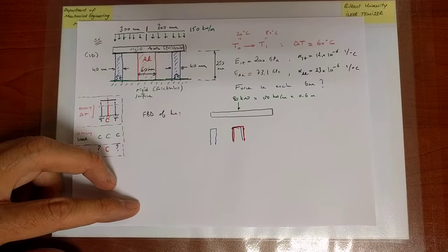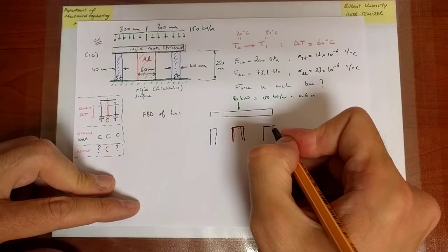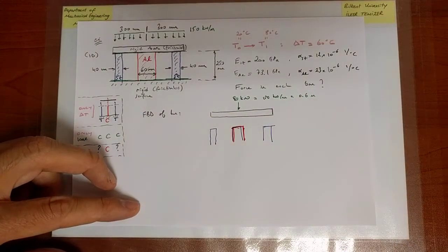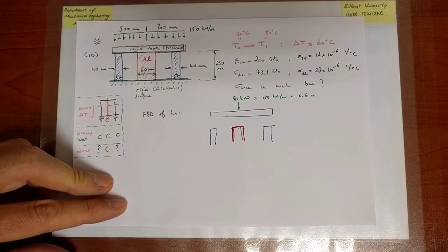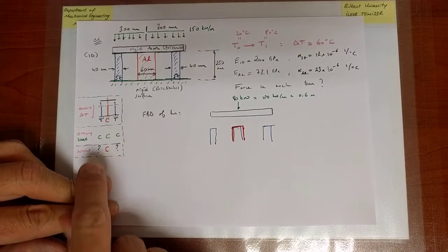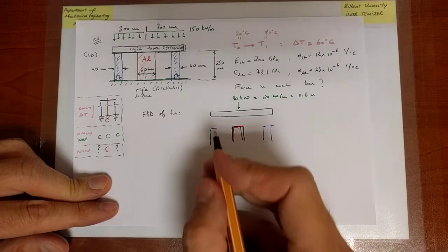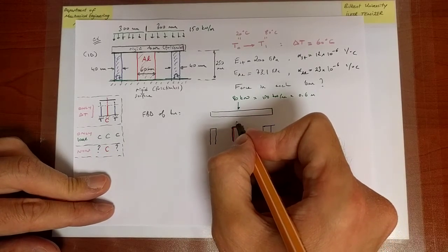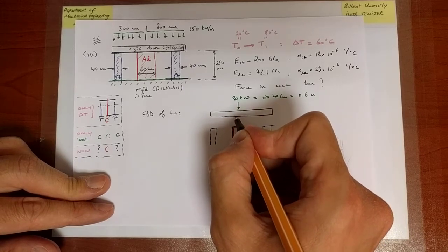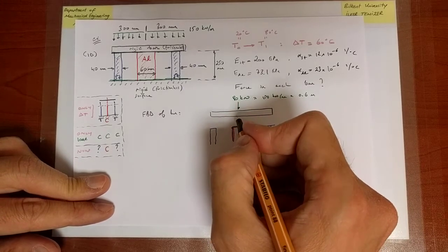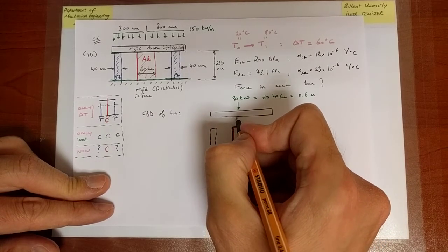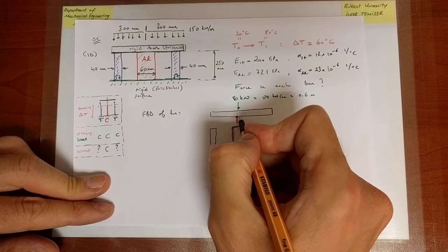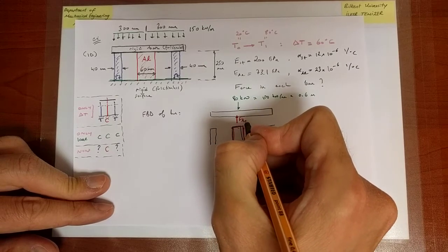And then there is the other aluminum bar. Now, I know that the aluminum bar needs to be under compression. So in other words, the force direction should be like this. So the force acting on the bar is equal and opposite. So I will immediately go ahead and write it as such. So this is force on aluminum.